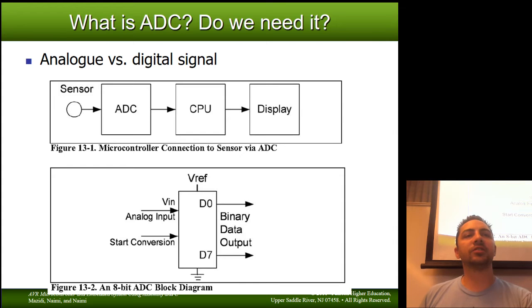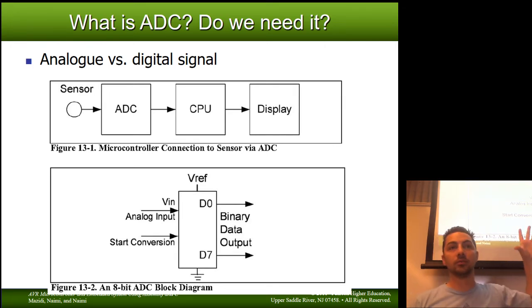So your average signal chain for any real-world signal is going to come from the real world, whether it's light or sound or vibration or heat. There's going to be some physical phenomena, and you're going to have a sensor or a transducer. Whatever that is doing, it's going to translate that physical phenomena into some kind of electrical phenomena, whether it's a current reading, so the current may increase, or a voltage reading, usually. It might be a resistance that changes, but something electrical that we can measure. And really, I've just covered Ohm's law, right?